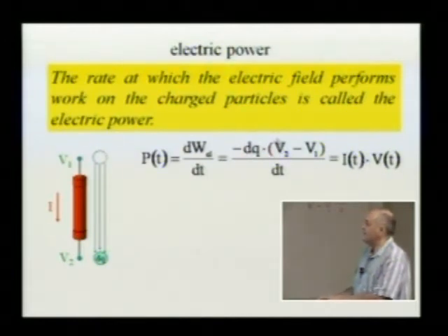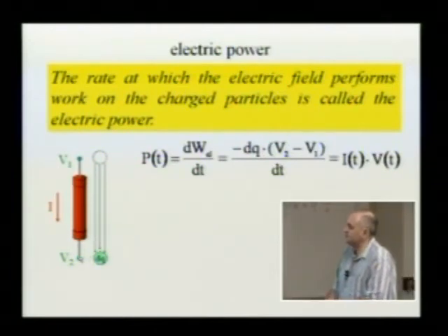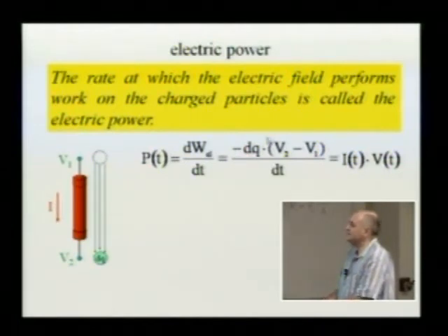So I can write that this is current multiplied by this difference, which is this potential minus this potential. It's inconsistent with the arrow. If I mark the arrow downward, it's the conventional current over here. So I combine this minus with this difference, change the order of them, and put voltage, which is this potential minus that potential.